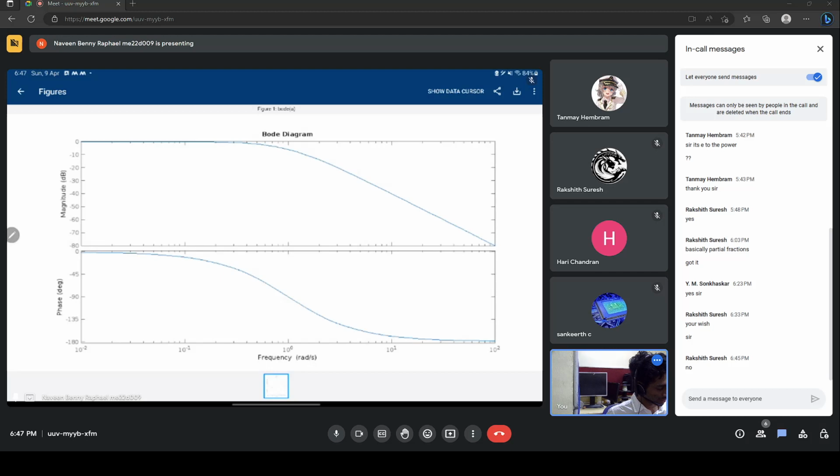Secondly, it now goes to minus 180 and not just minus 90. That's because naturally it has added it twice. Because when you add the two plots twice, it will go from 0 to minus 180. Did that make sense? I don't think it did.